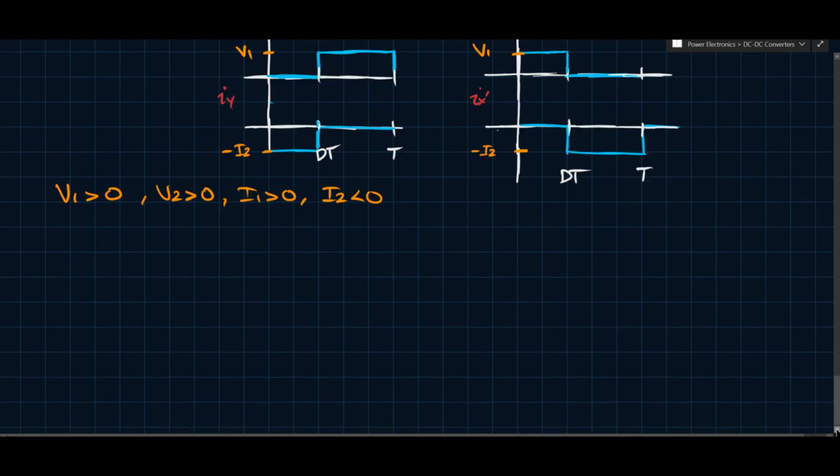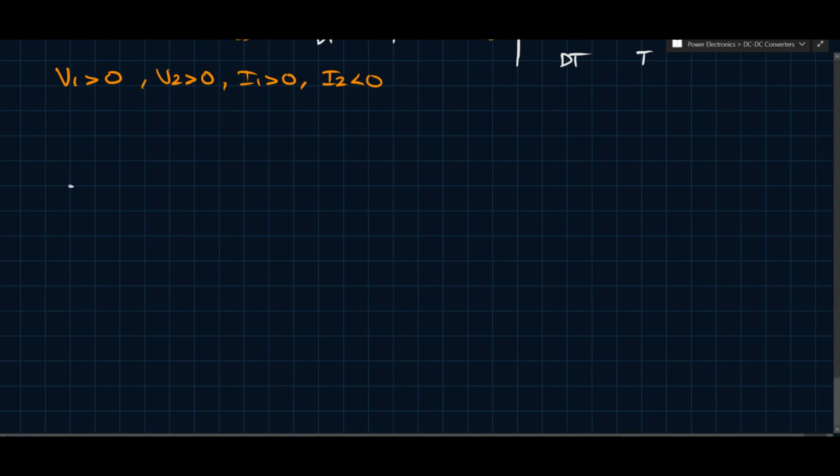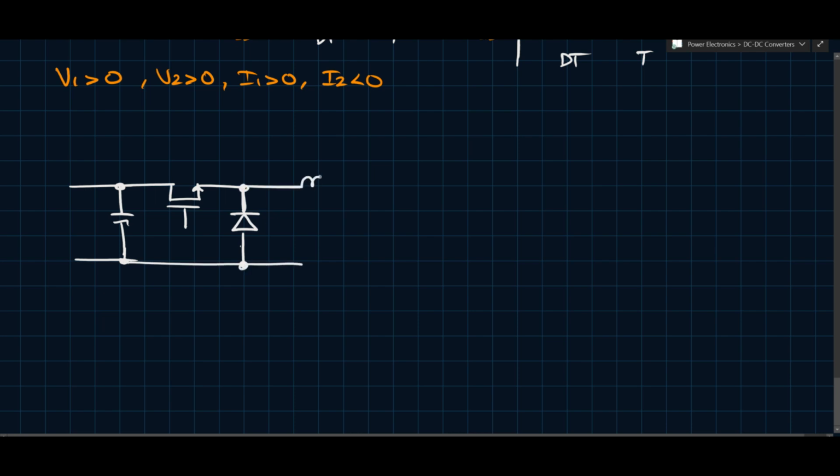So what we're going to do is create the buck converter, or a practical version of the buck converter. Okay, so we're going to say that the input is a capacitor, because you always need your filters no matter what. And so you have this filter, and again, this XY switch, we're going to say it's a transistor, so we're going to draw it as a MOSFET, because that's the most commonly used transistor these days. And this shunt element is the diode. Okay, and again, this is the practical sort of circuit, if you were to put a circuit on a breadboard that were to act as a buck converter, it would have to look like this. You can't use these ideal switches; they don't exist, right?